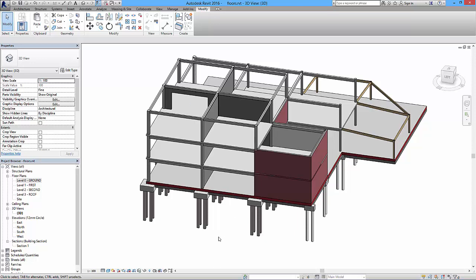Right, this is part 3, and we are looking at curtain walls in this one. Applied exactly the same way as walls are, but there's a little bit of jiggling around with grids on the curtain wall as well. So you're going to add a grid and then turn that grid into a mullion and basically change the panels. You have a couple of basic panels to start off with, a solid one and a glazed one, but you can, again, as it's a family, and it behaves the way that families do, you can update it and change it and do whatever you like to it.